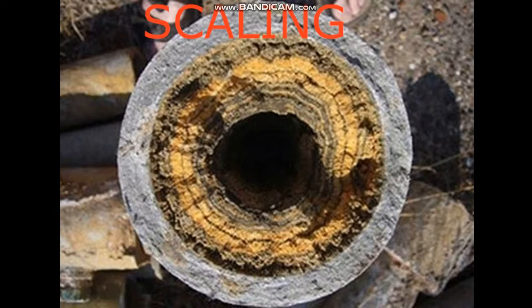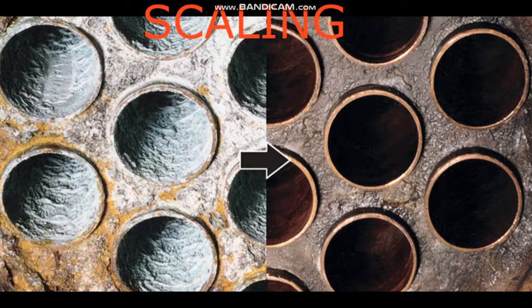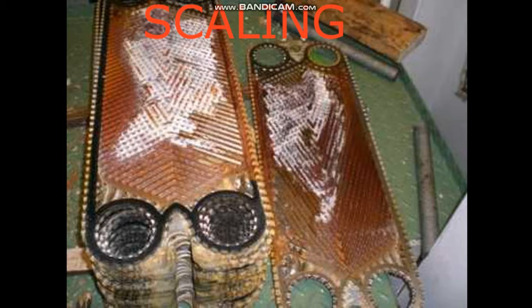Scaling is the most common type of fouling, and is commonly associated with inverse solubility salts, such as calcium carbonate found in water. Reverse solubility salts become less soluble as the temperature increases, and thus deposit on the heat exchanger surface. Scale is difficult to remove mechanically, and chemical cleaning may be required.